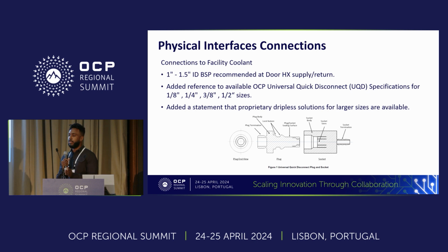And we also added a statement that they are proprietary dripless connections for the larger sizes, meaning those 1 to 1.5 inch, because they're not covered under the UQD, Universal Quick Disconnects. But you can ask companies like CPC, Danfoss, etc., for those dripless 1 to 1.5 inch connections, or large bore.